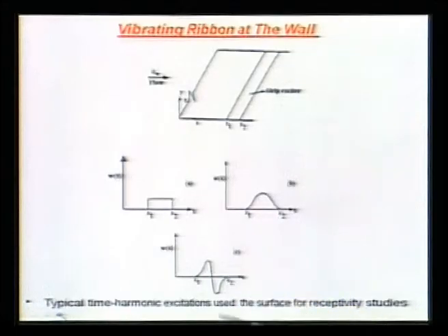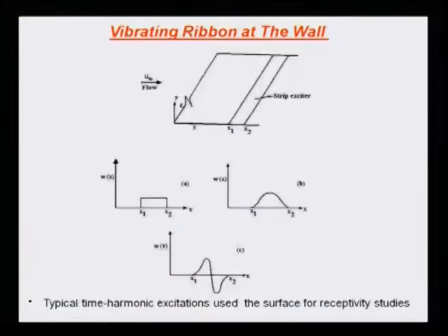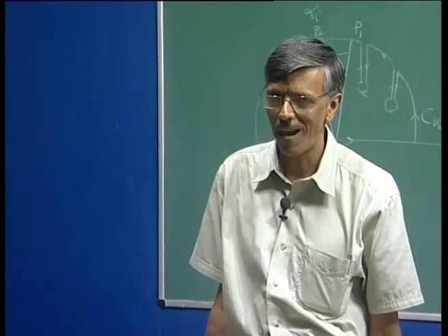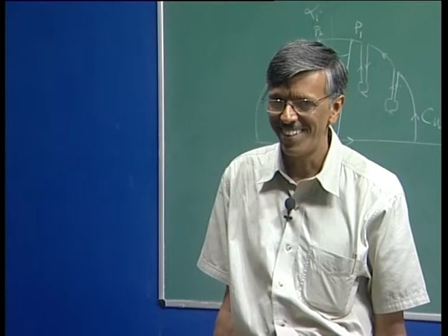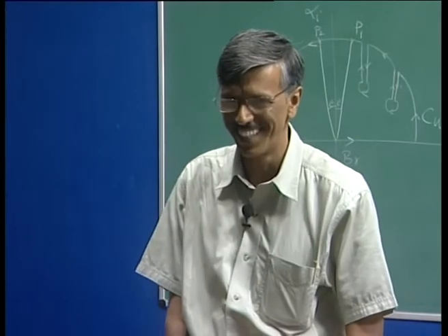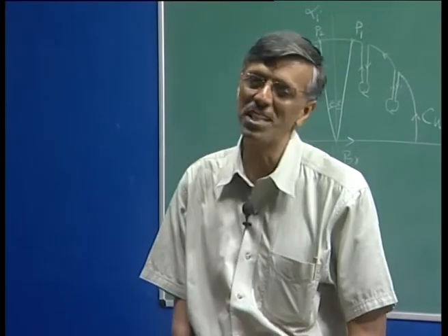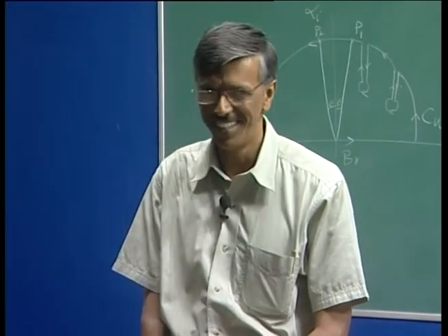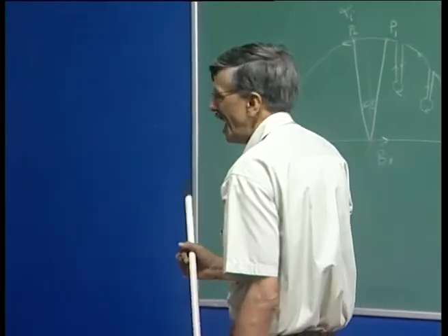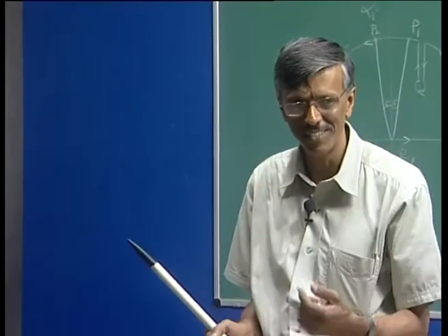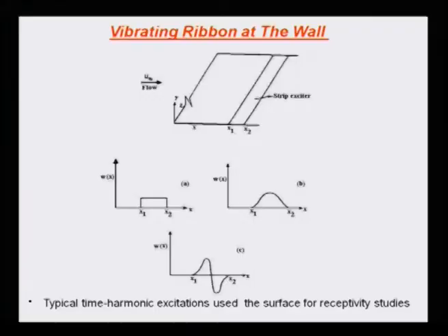Instead, you would like to have this. And what is this? In the limit, suppose x1 and x2 approach 0, what do you get? It is a double delta function, which has a very specific name. This is called the doublet, isn't it? So a doublet is nothing but the first derivative of the delta function, right? And that's why the delta function doublet behaves like a vector. It has a direction going from source to sink. So these are the kind of things that one can talk about.